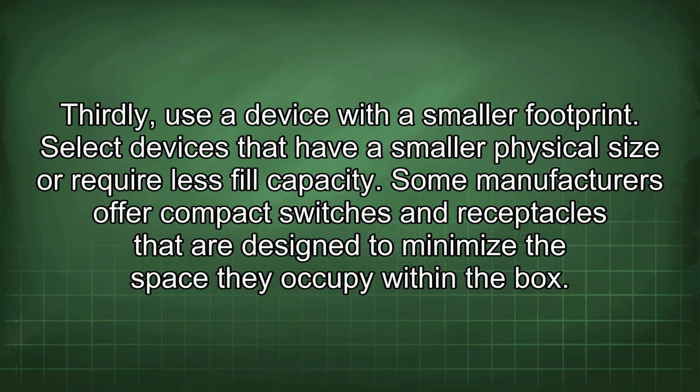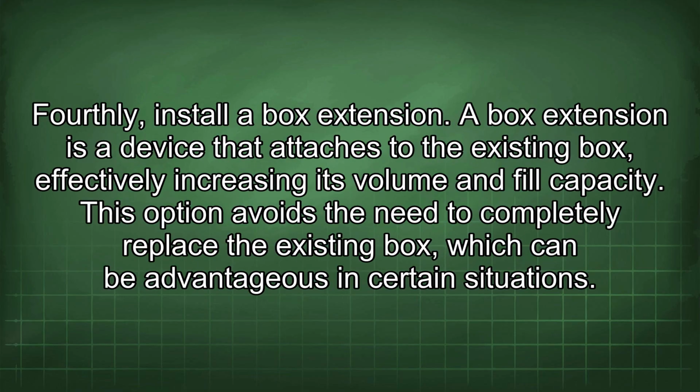Thirdly, use a device with a smaller footprint. Select devices that have a smaller physical size or require less fill capacity. Some manufacturers offer compact switches and receptacles that are designed to minimize the space they occupy within the box. Fourthly, install a box extension. A box extension is a device that attaches to the existing box, effectively increasing its volume and fill capacity. This option avoids the need to completely replace the existing box, which can be advantageous in certain situations.